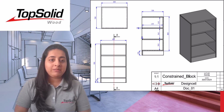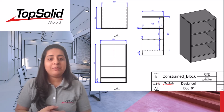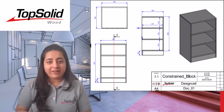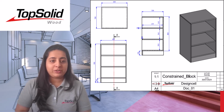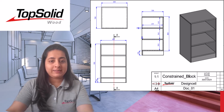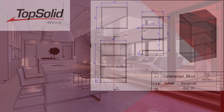In this tutorial, we will learn about constraint block and its application. The constraint block function is intended to simplify and automate the positioning of rectangular shapes, mainly used to create panels for your furniture. Let's try to create an open base unit like this using the constraint block function. Width is 600, depth is 500 and height is 900, as you can see.